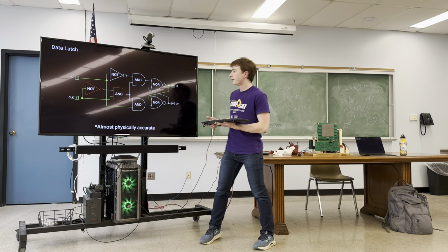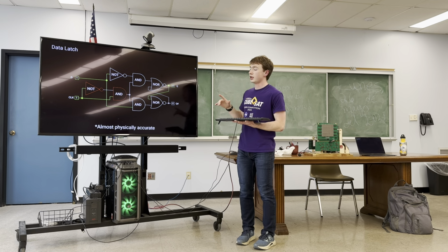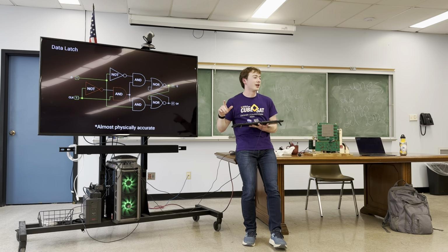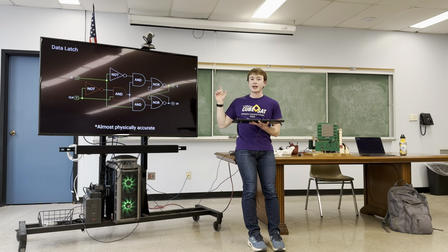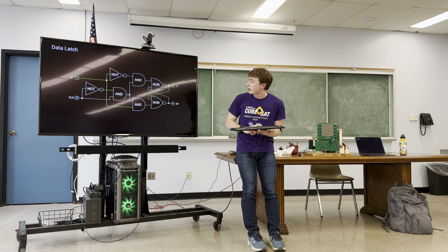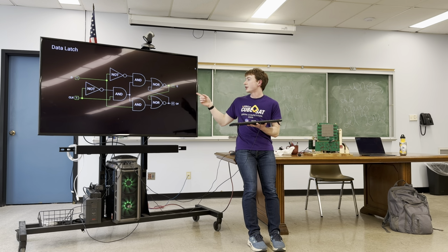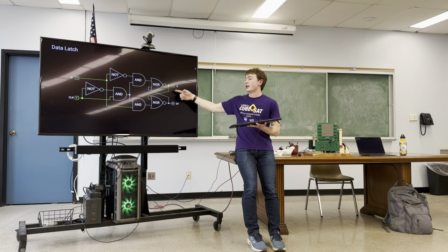This means that if the clock is either just high or low, the data input can be whatever you want and it won't affect the output, and it'll latch the data into the circuit. As long as it has power, it'll stay like that. This is just a demonstration of how it works. Watch, this only updates whenever the clock goes from low to high.